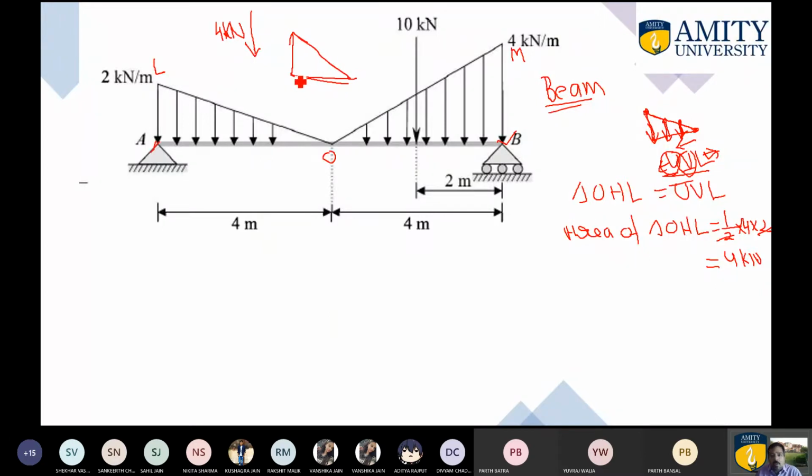So if you recall the formula for center of gravity, if you are moving 90° from over here, then you are required to move a distance which is equal to base by 3, and you are required to move a perpendicular distance which is height by 3. The point at which you reach is basically the center of gravity of this right angle triangle. So this is how you are required to calculate the center of gravity.